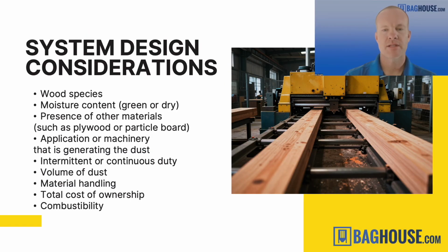System design considerations. When we look at designing a dust collection system, we'll look at the dust type and size, fine versus big bulky dust and chips and so forth. We'll look at moisture content, and this normally is not a huge factor when we're talking about wood shops, but it can be, if you have a lot of moisture, that can impact the filter media. We would want to know that up front.